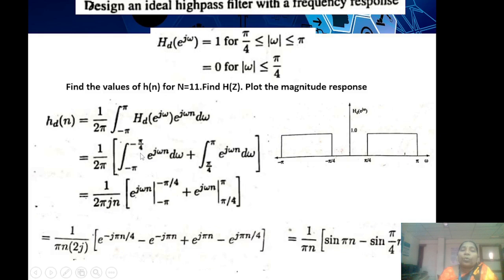From this equation, we have to write down the h of 0, h of 1, 2, 3 and all. So how will we be writing this? If it is z power minus 2, the value associated is h of 2. Like that, and h of 2 is symmetric with h of 8, so that's why it is equal to 0.075. Similarly we'll be writing this.